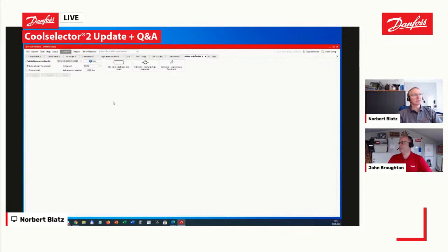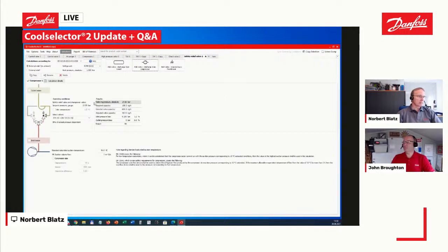There is an issue when it comes to CO2 applications, because CO2 reacts quite differently compared to standard refrigerants. One is that it becomes solid at ambient pressure or even above ambient pressure. And then also it has a high difference between density of liquid and vapor. And this needs to be taken into account while selecting a safety relief valve for such a system.